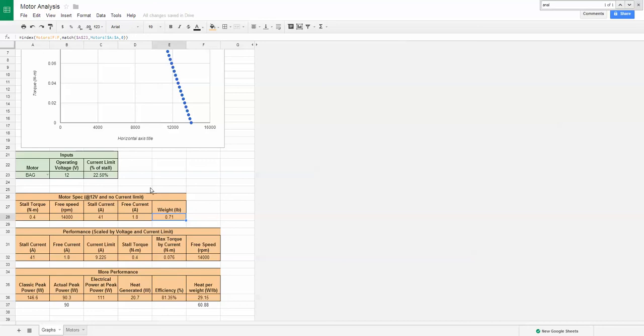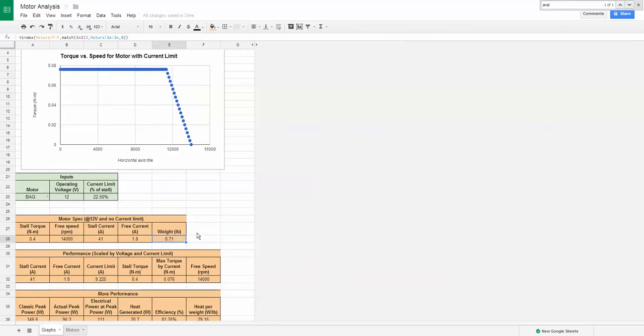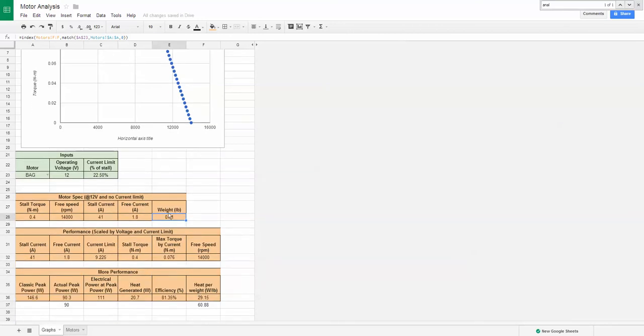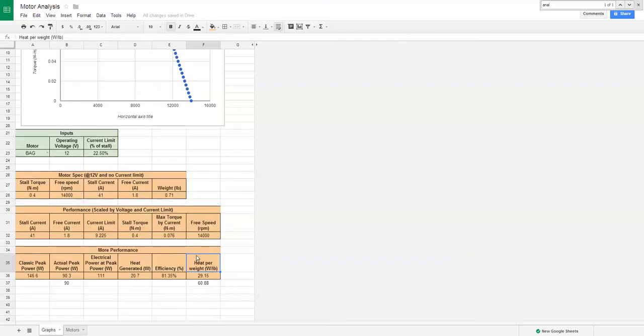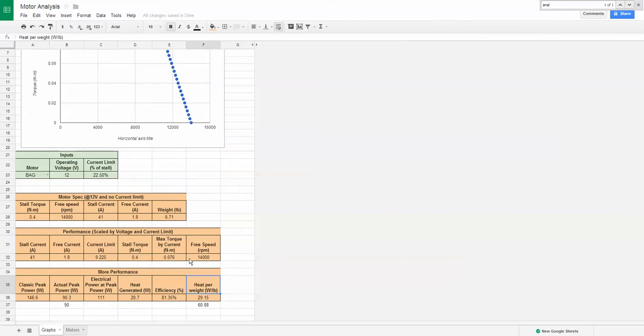So kind of what we just proved here, and I think some people may take a couple peeks at this video before they really believe me, because there's a lot of math here that I really skipped, is that a more efficient motor with more weight and, although that's not shown, the ability to dissipate heat better, which I feel like the bag would probably dissipate heat better than the 550, can sustain a comparable power output with less heat made, or it can sustain a higher power output with the same heat made. And essentially there's going to be some number in watts per pound for each motor that would have to be tested that would tell you whether or not a motor will fail.